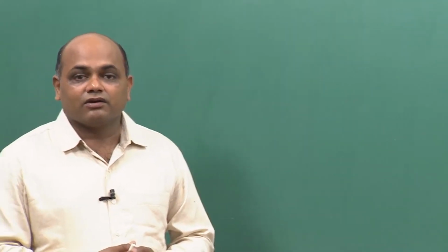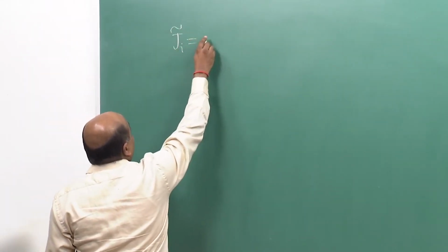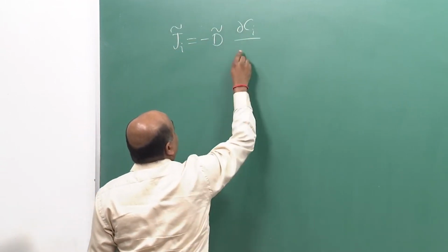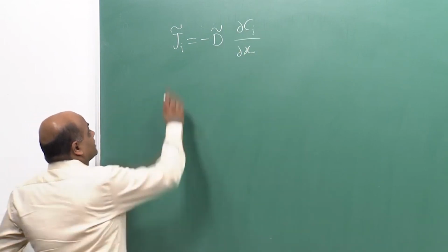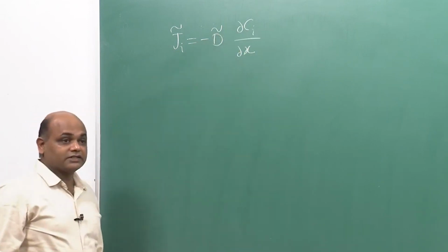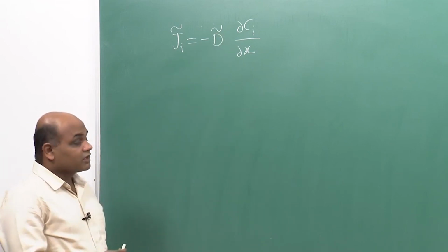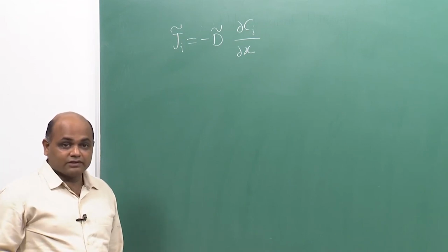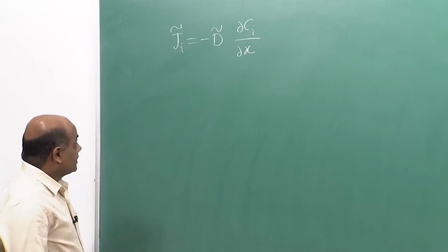So, the diffusion flux of both the components is described based on only one interdiffusion coefficient, and this interdiffusion coefficient again varies with composition. So, if we write Fick's law for the binary system, we write J_i tilde, where the tilde sign again denotes that we are talking about interdiffusion or intermixing, diffusion along strong concentration gradients.